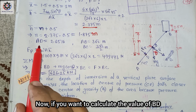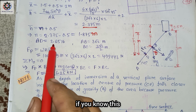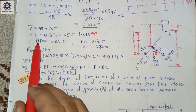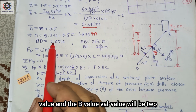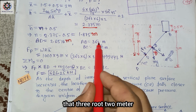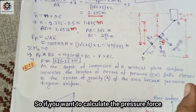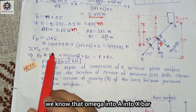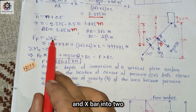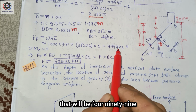Now if you want to calculate the value of BD, how to calculate it? If you know this n value, this is 1.875 and this is 45 degree, so from here you can calculate the BD value, and the BD value will be 2.6516 meter. And AB we know is 3 root 2 meter, and BC is 3 root 2 by 2 meter. So if you want to calculate the pressure force, we know that omega into A into x bar, omega is rho into g into area, that is 3 root 2 into 6 and x bar into 2. So from here you can get the pressure force, that will be 499.43 Newton.